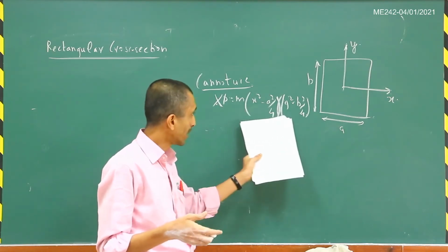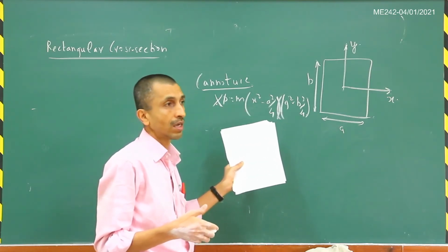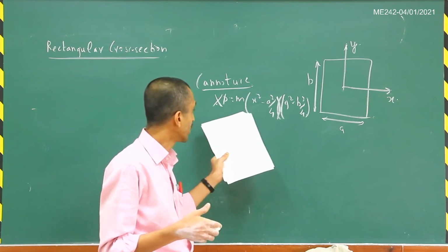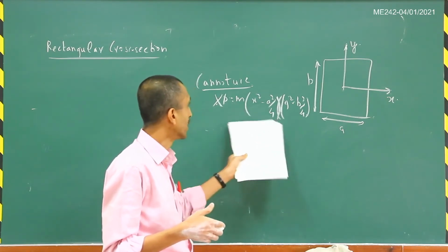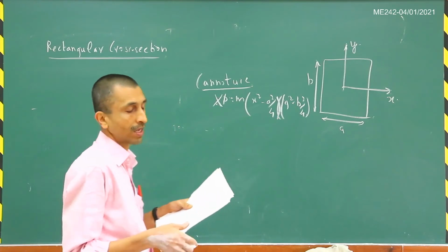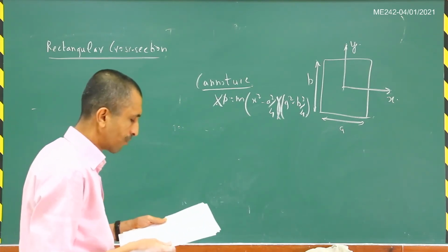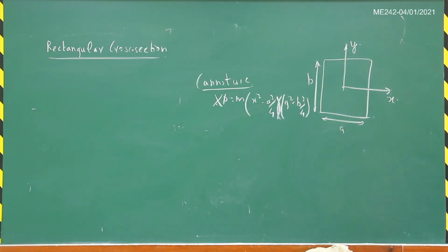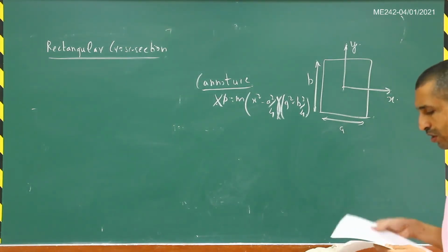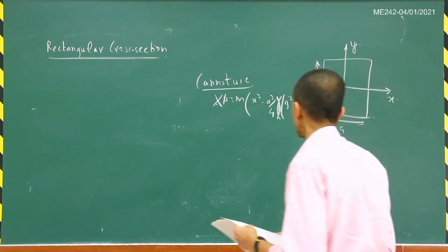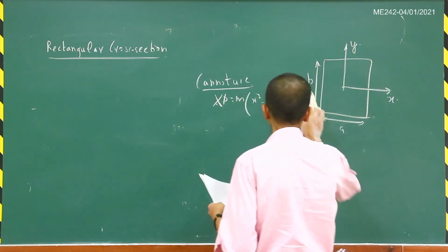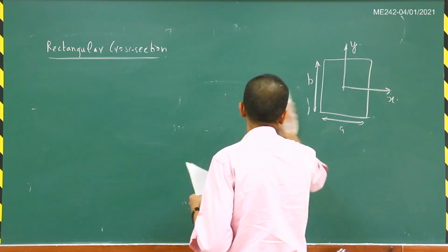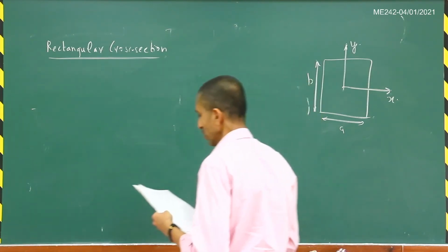So if you take this to be the equation for the Prandtl stress function, then you will not get del square phi to be a constant. And so we have to follow some other approach here. And so actually this is a very nice example to introduce a Fourier series kind of solution here. Okay, so let us now find the solution by writing the equation for the conjugate function here.